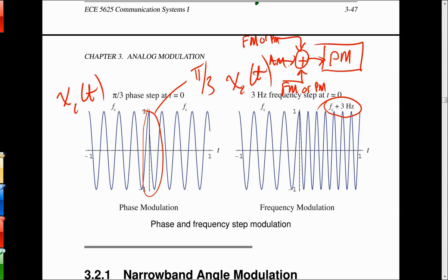So you can put signals on carriers using any of the three modulations we've now talked about: the amplitude, double sideband or AM, FM or PM. As long as those carriers are distinct from each other, when they're summed together, they can go into another stage of modulation, and when you get to the other end and tear it apart, they'll be intact. And we'll be learning eventually that's how FM stereo works. If you've ever wondered about that, that's a 1948 vintage technology, but they figured that out a long time ago, that they could use what's called subcarrier modulation for FM stereo.